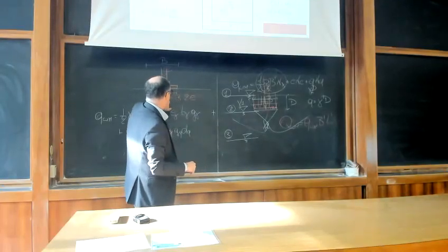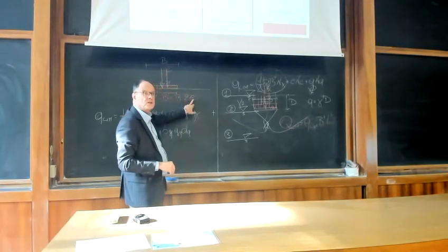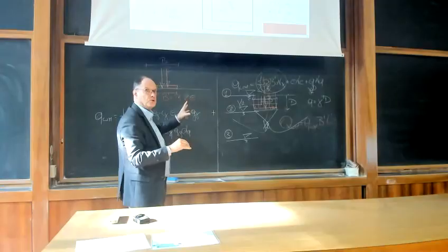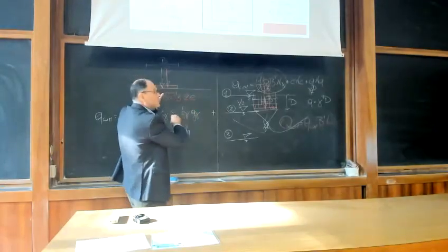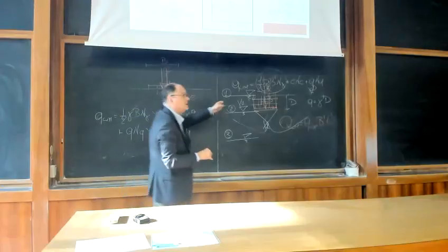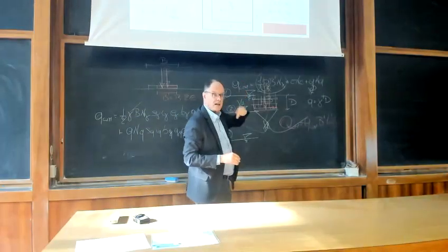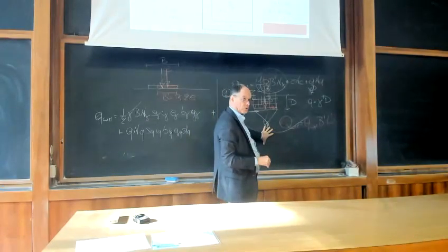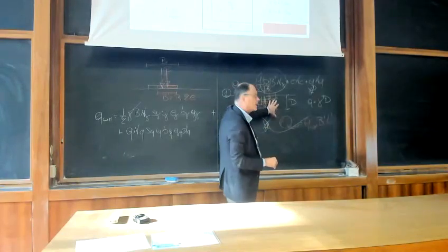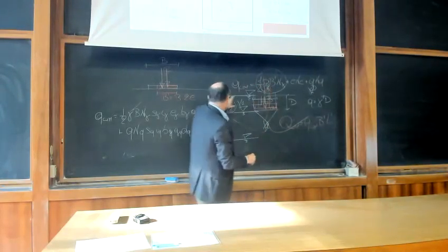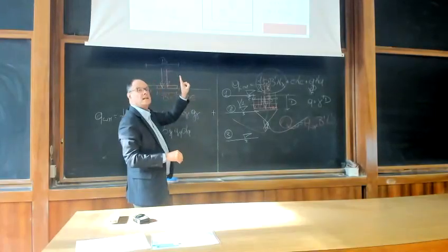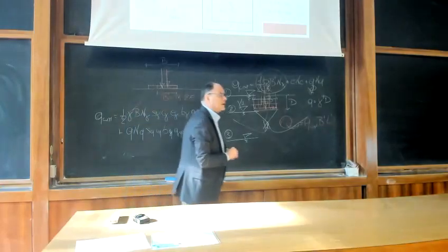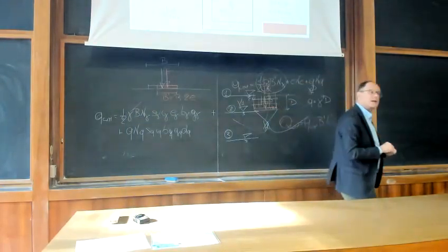Now consider that this becomes a function of the eccentricity, and so becomes a function of your resultant of the loads. So if you change the size, if you change this distribution of load, you can have a different capacity. So once again, the capacity is not only a function of the soil, it's also a function of the size of the footing, and in this case also of the eccentricity of your resultant, so of the applied load. And the same way if the resultant is also inclined.